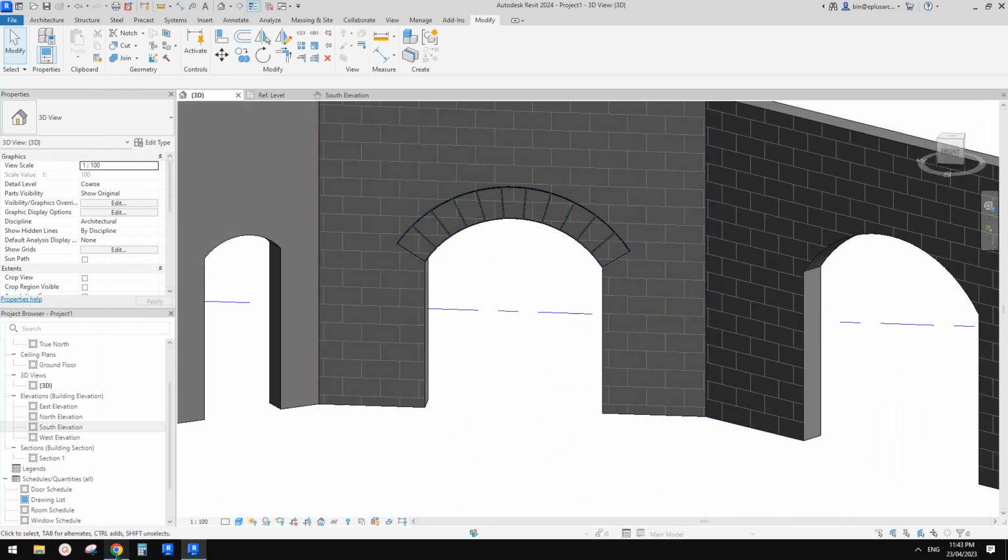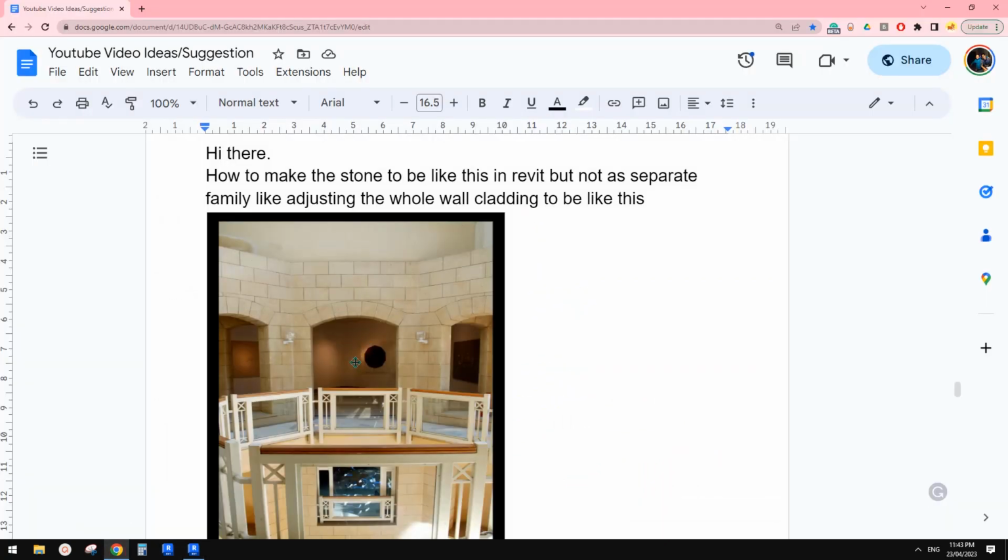Basically, if you just need to show them in elevations or basic Revit 3D view, you can use the pattern for the main part, and for this one you can just use a different material with some manually drawn lines, model lines or detail lines even, but for render it can be a little bit trickier.